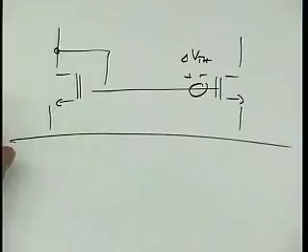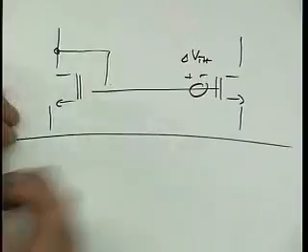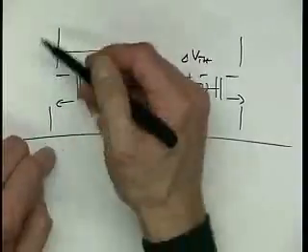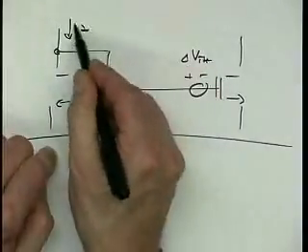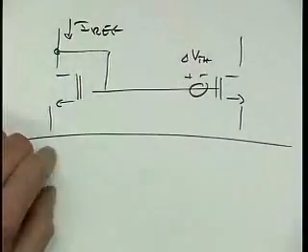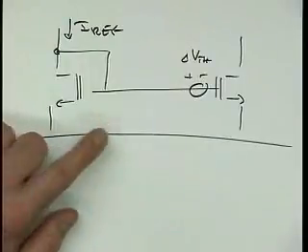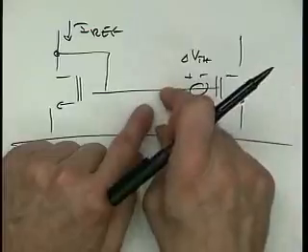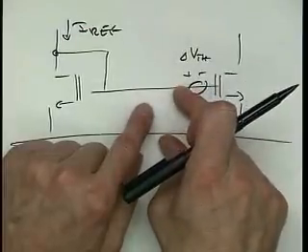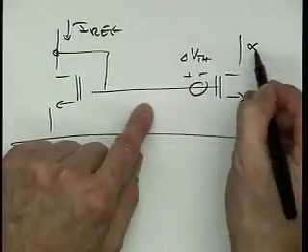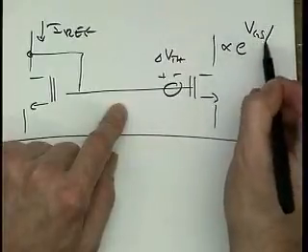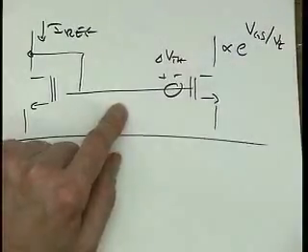Should be 0, but it's not. So this device computes the right VGS to run whatever IREF we stick into it, right? So then this device over here goes and takes this voltage, amplifies it exponentially, and runs the output current.